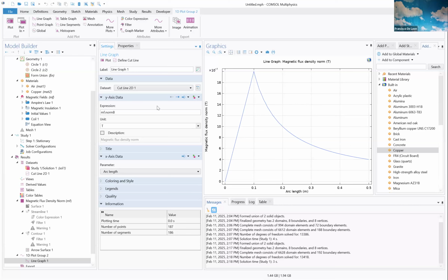We put only one current, right? We shouldn't put only one current, never, because the current needs to come back somewhere. You're violating the continuity of current. If you increase that length to infinity, it will come to almost 0, some exponential, but it will never be 0. And if you were to integrate, the energy will give you infinity.